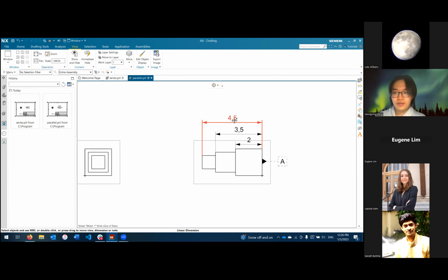If we give a nominal dimension, or a plus-minus dimension, I should say, with a number in the middle, some machinists will still do the same thing where they'll stay near the top dimension, but others might try to go for gold and go for that number that's called out in the middle.